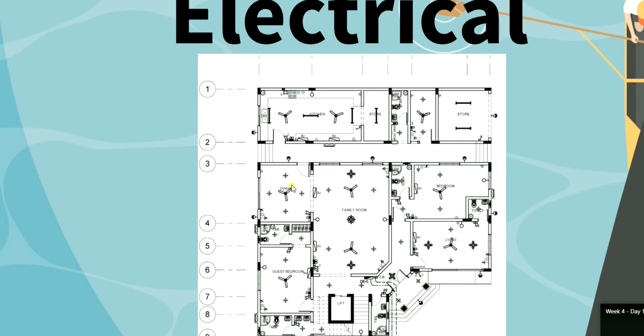Before giving the drawing to the contractor, you need to do two things. First, you need to send the architectural and structural drawing to the municipality and get their approval. If there are any changes required, you need to implement them, and then get the drawing stamped by the municipality for architectural and structural.